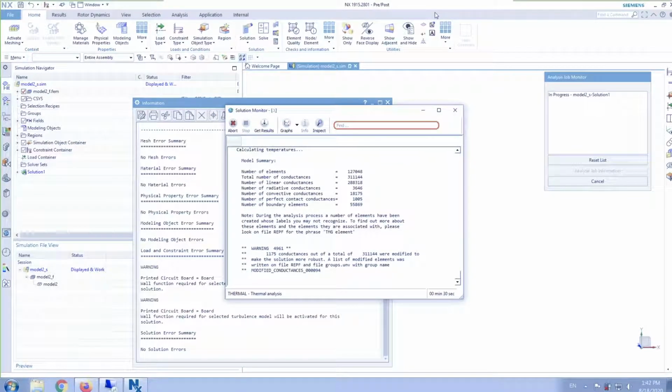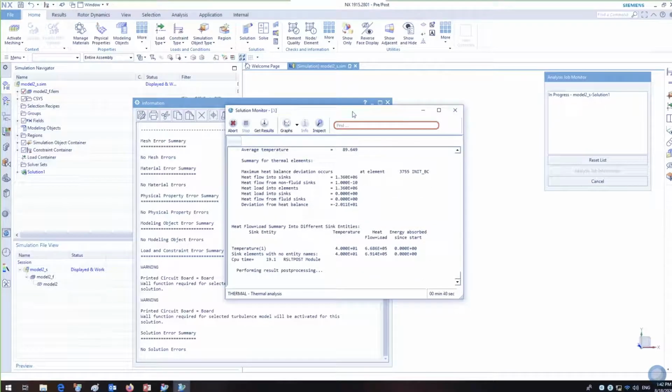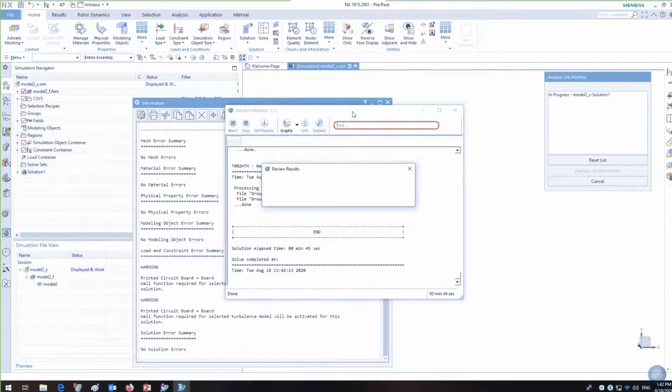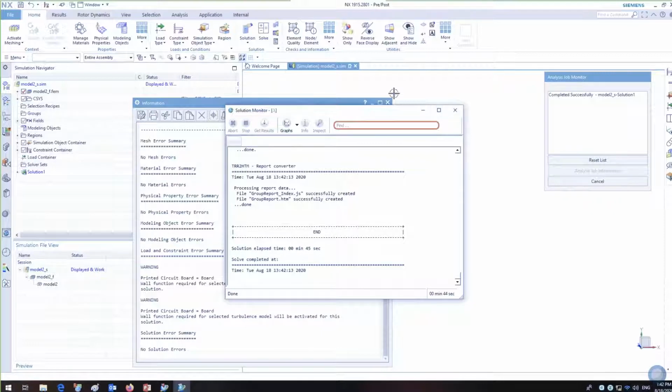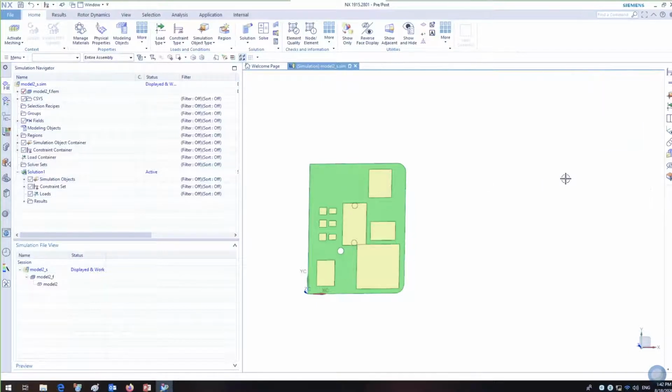I think we got a question in. The question is, can you model just the most significant components and then smear the rest of the heat directly on the board? And that is yes. We actually have a filter, so we can filter components based on their catalog dissipations. Components that have lower than, let's say, 0.5 watt dissipation, we could filter out.